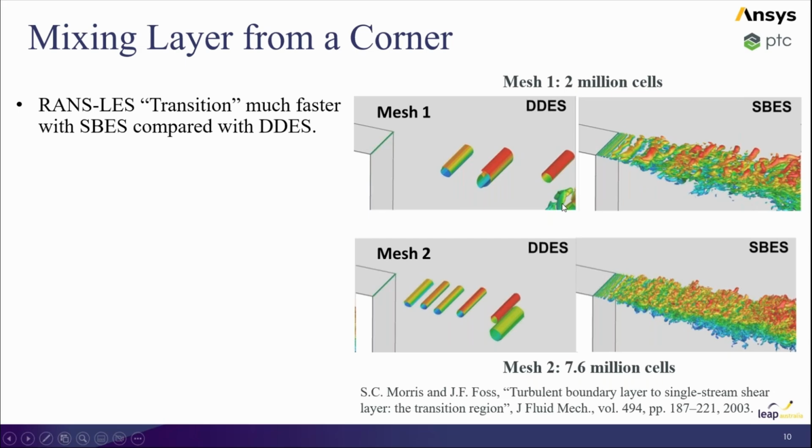It starts to do it here. This is very typical of what you see in a URANS model. So you basically have these perfect cylinders with a size that's determined by some feature of the geometry, not necessarily physical, because of the way the source terms are written in the code and were designed.